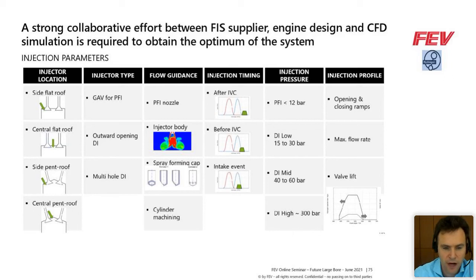Also injector type, the flow guidance, injection timing, the pressure that we are discussing about, and the profile. And all together will, for example, for hydrogen, play a major role regarding mixing. And that's why there is not one good or right answer at the moment, but we have to have a holistic approach where we consider all these several aspects of the combustion system and of the injection system, and the strong cooperation between the fuel injection system supplier and the engineering side that is dealing with the CFD analysis and charger motion design. So these have to be even more intensified than before.